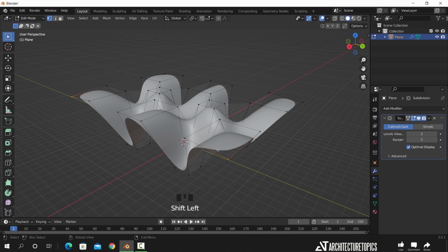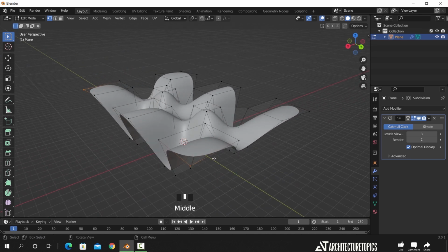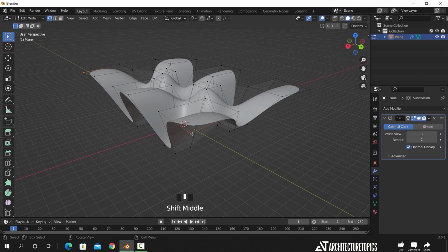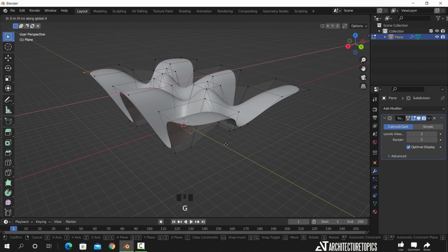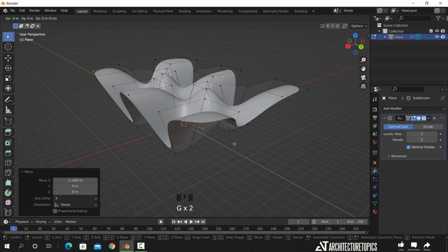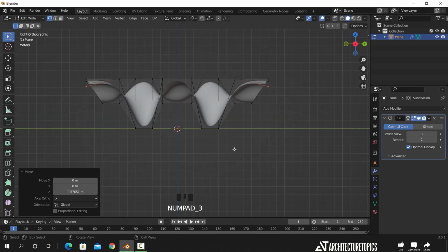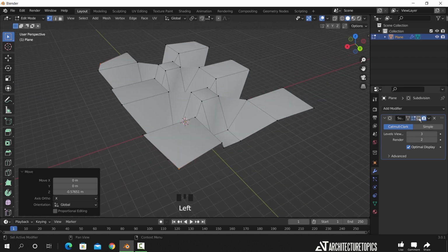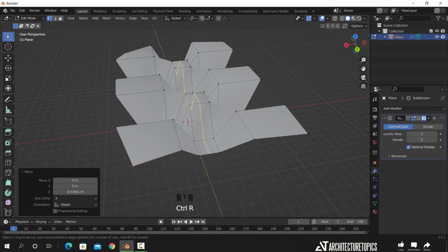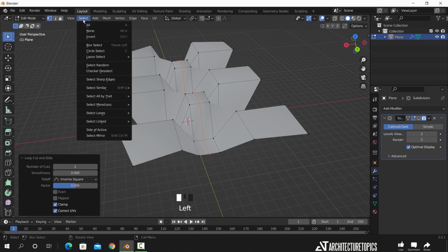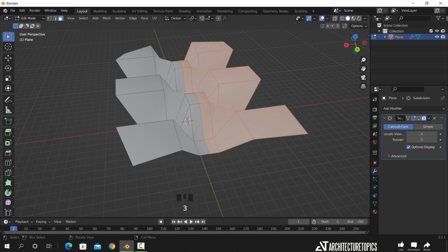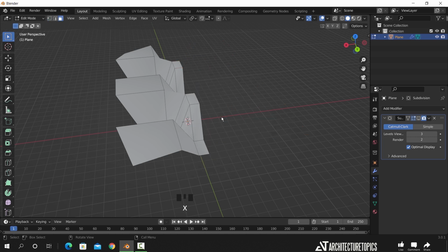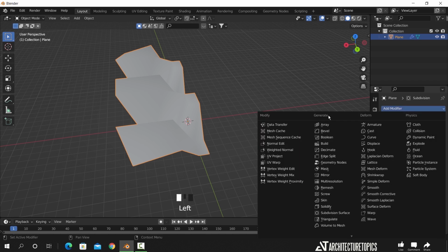We can move those 2 vertices to the back and give it more curvy corner from the top. Now to keep the symmetry on both the front and back sides, I will add a segment here and cut half of the shape, then use a mirror modifier to complete the shape again and make it easy to edit it. And try to keep the modifiers in order.